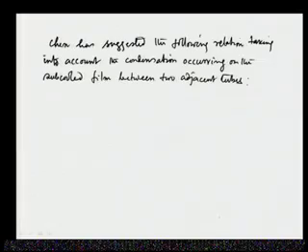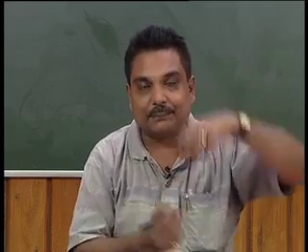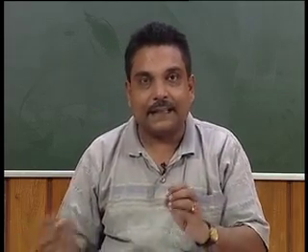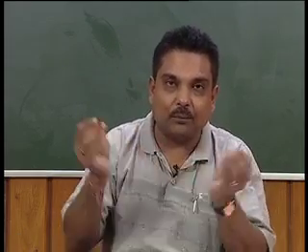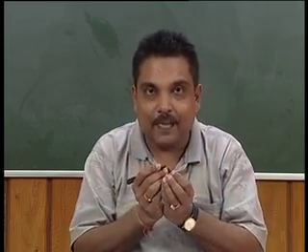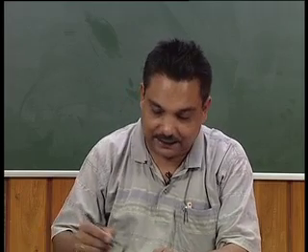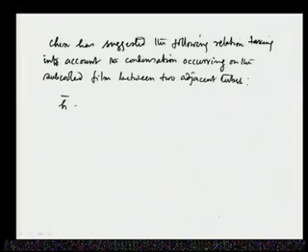So, as we have seen previously, when there are two adjacent tubes, there is an expression for h bar that we have found. But what may happen is that there could be a subcooled region where some condensation of the vapor may take place, so some corrective measure has been taken, and Chen has given that information. According to him, h bar is equal to 0.728; it is marginally changed, it was 0.725, and now it is 0.728.